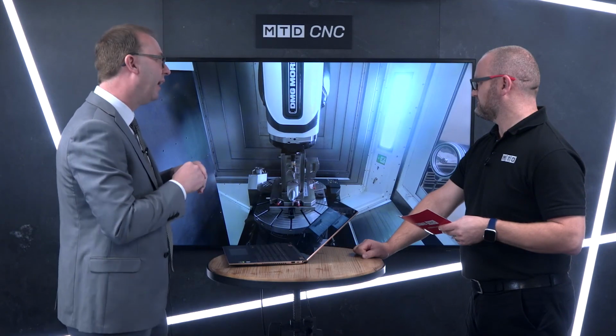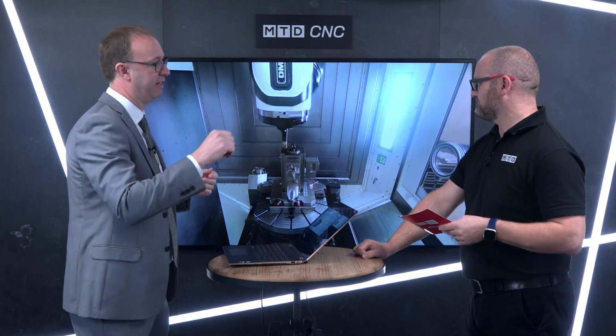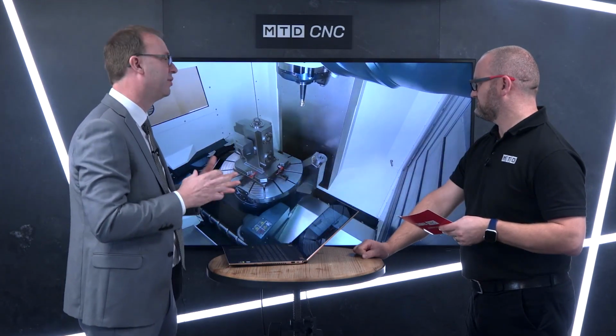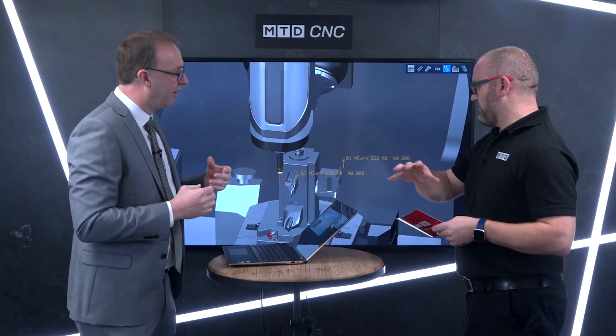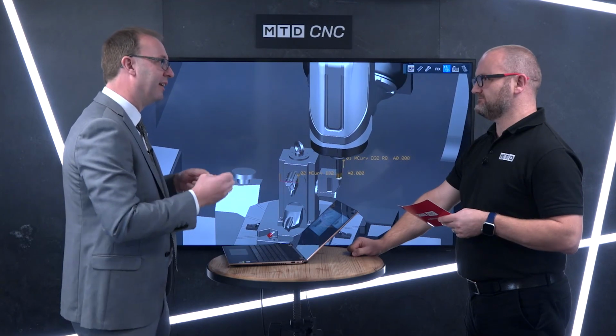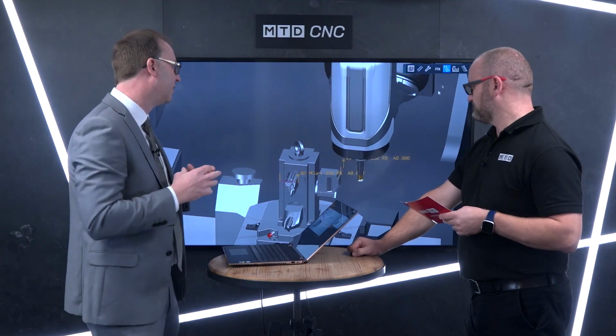Now why is this important? Because a lot of systems don't control the connections between the end of one toolpath to the start of another, which essentially is very dangerous because the controller takes over at this point, and we don't know where the collision is going to appear, if there's a collision going to appear in between. It could even be things like the tool changes. We can simulate the head changes all in one virtual machine. Okay, and you can see... Again, working with your tooling library. Absolutely. So all of this all links in, it all feeds in together.